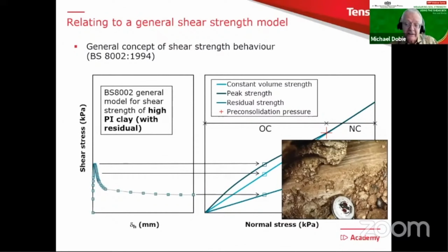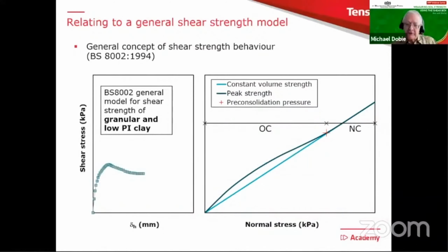But that's London clay. London clay has a residual phi value of about 8 or 9 degrees, which is very low, of course. But this is an important thing to be aware of when you are reviewing the results from shear box tests. So before leaving this, I thought I'd just take one particular point. Let's go back to this diagram. And I'm going to put on here 3 possible results from shear box tests. There they are, the red squares.